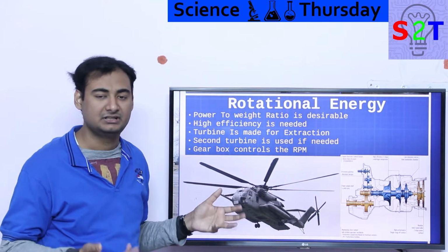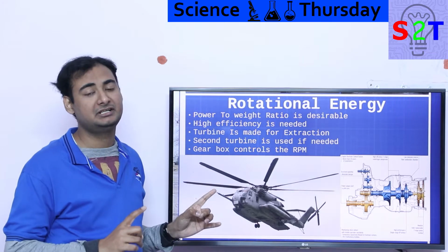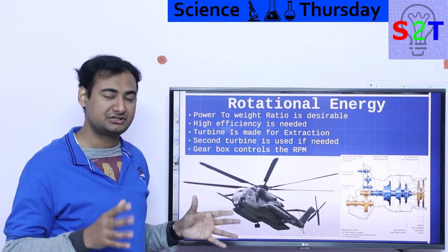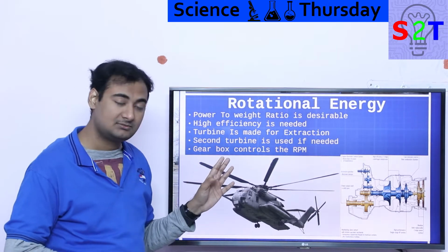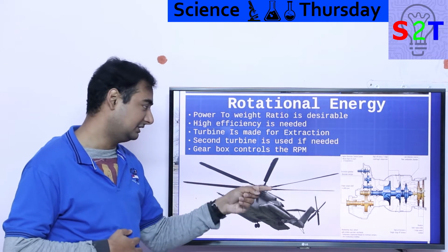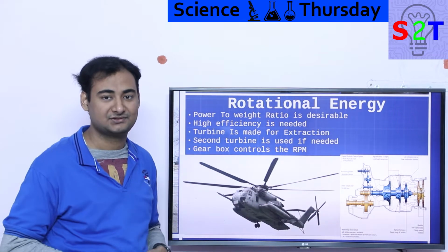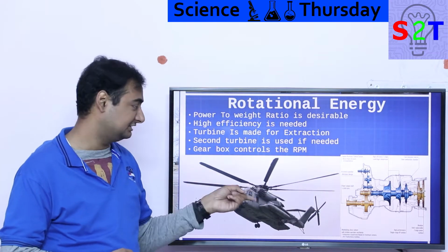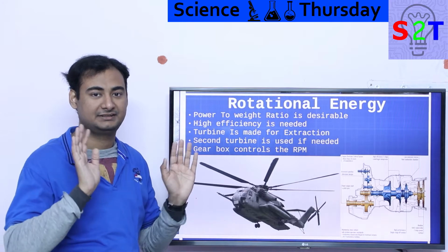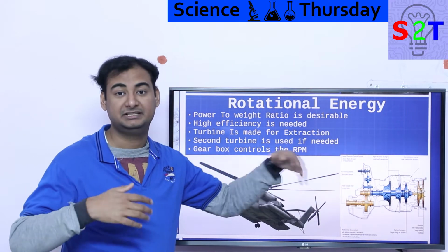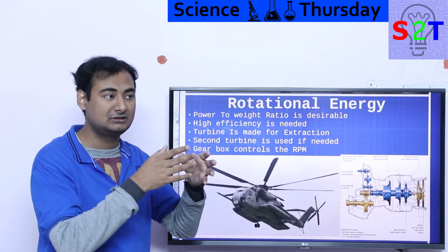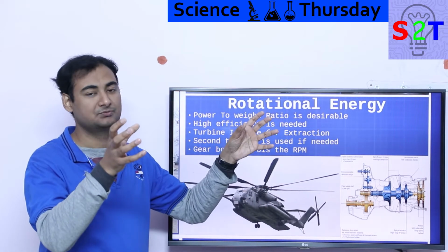And gearboxes are generally implemented, generally planetary gearboxes, simply because they are much more efficient in terms of size and weight. However, they are ludicrously expensive. Generally gearboxes are used to control the RPM, because your jet engine can be as high as 5000 RPM. You send 5000 RPM to a giant helicopter rotor, it's like, yeah bro, bye. So that's how we extract rotor energy. Basically, we just add either a secondary turbine stage or improve the main turbine and make it much bigger.